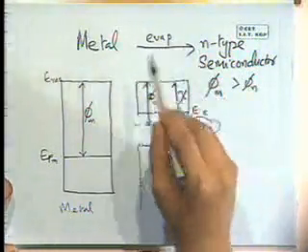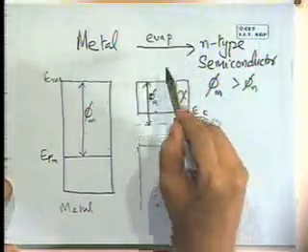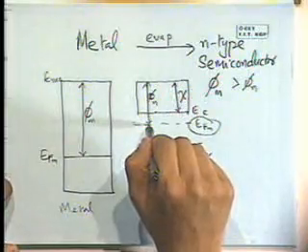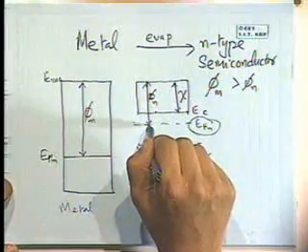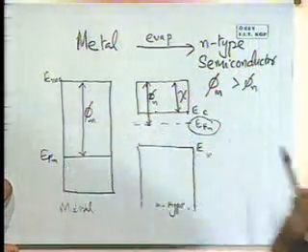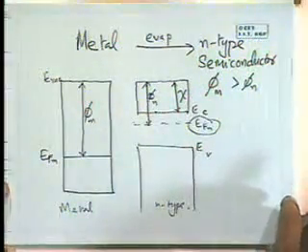So the sum total of all those energies, when you consider, effectively what we have is that the minimum energy that you will require to get an electron out of the semiconductor to the vacuum level is still phi n, same as the definition for the metal work function.